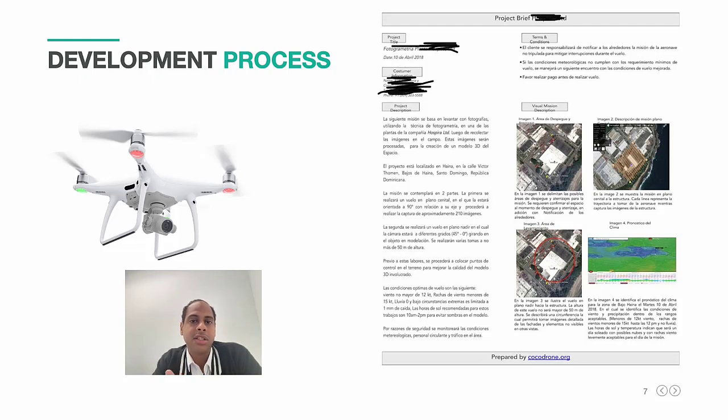We may use, for example, software in order to program the drone. We're going to check the wind conditions, the height, the time. Normally it's very useful to fly the drone between 10 and 2 p.m., because that's when the sun is at its zenith, so shadows are avoided.